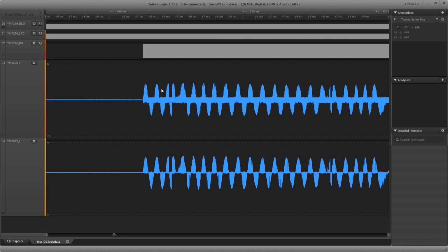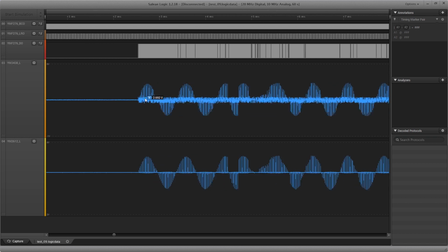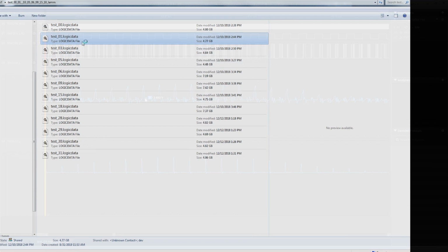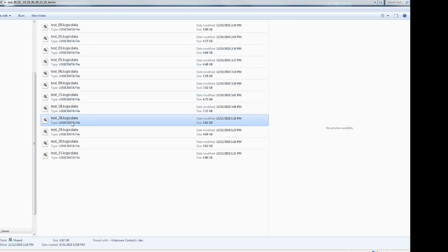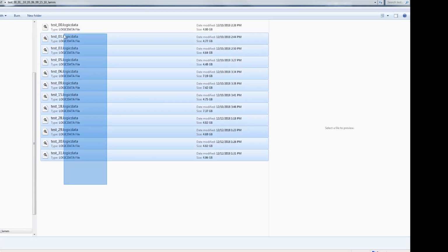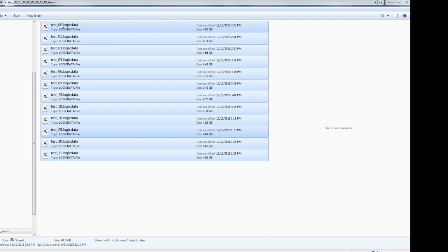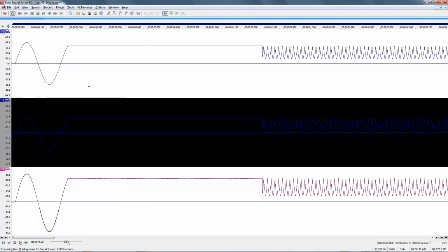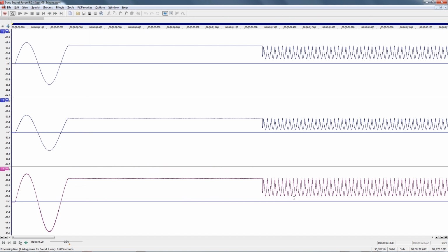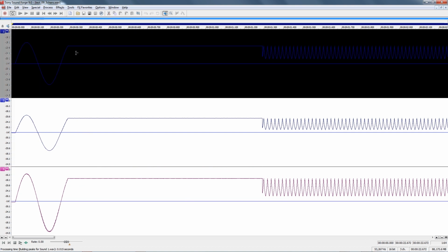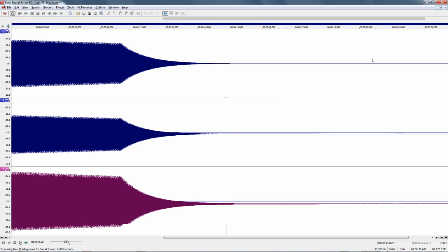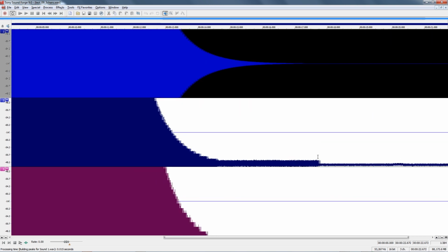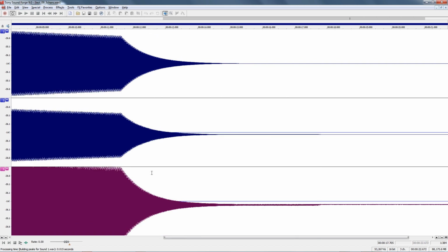Sampling both analog chips at 10 MHz and the digital one at 20 does take a load of memory. Each test takes upward of 8 GB of raw data, which you can see here. In order to make this data usable, I coded something to convert this into a 3-channel 53 kHz wave file, with the serial digital stream for the OPN2L being done bit accurately, along with the synchronized discrete analog values of the 2 other chips, timed to the clock output of the OPN2L.